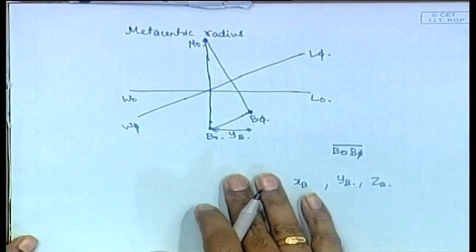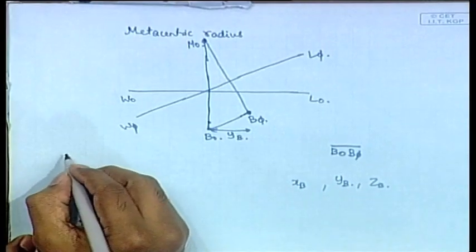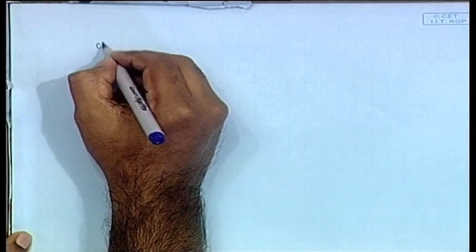How to find that? Therefore, I will write here. Now, this is just like your previous problem where you shifted a mass from one point to another and you saw that the center of gravity shifted. Just like that, here a volume has changed: there is a volume decrease on this side and a volume increase on the other, because the body has come like this. So, it is like a volume has shifted from one side to another, and as a result of it, what will be the change in B?